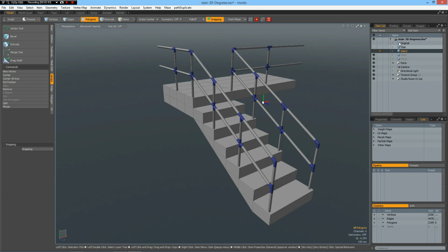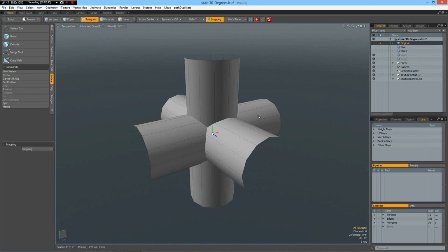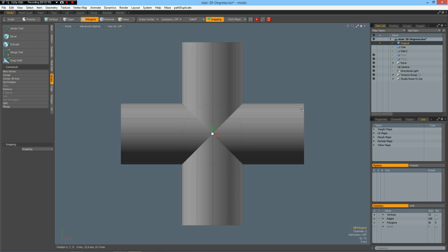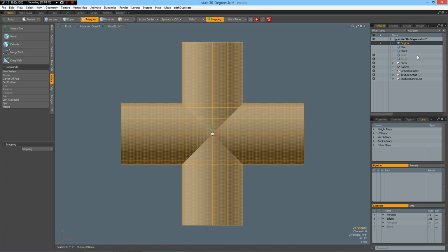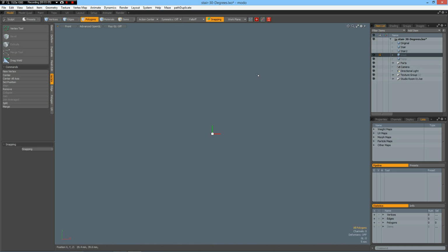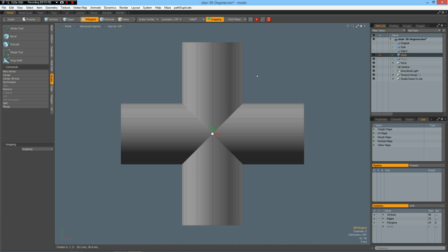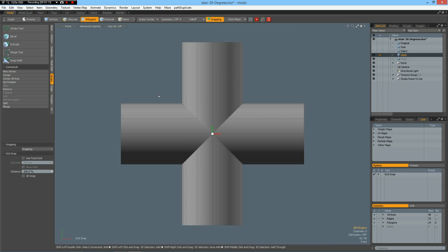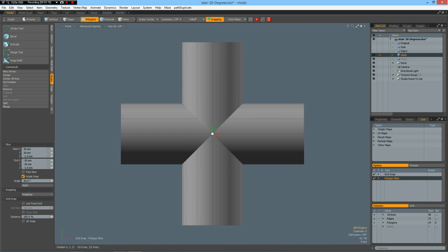I go to the original where I have prepared something, and first we do the really simple ones, which I have partly covered in other tutorials, but just for the sake of it I'll do it again. So copy these, Control copy, go to the work mesh, Control V, then F11, go to snap on grid, Shift C, and cut through.